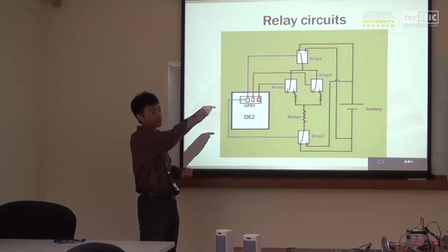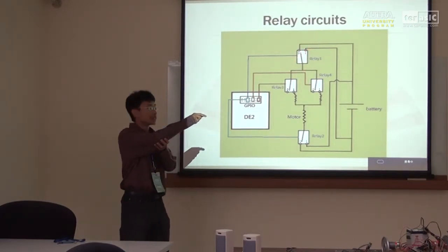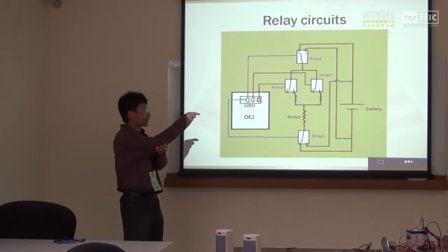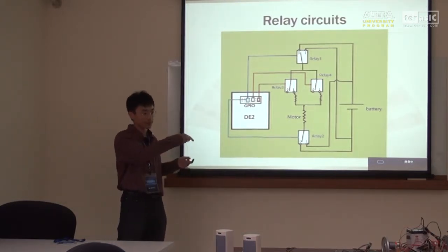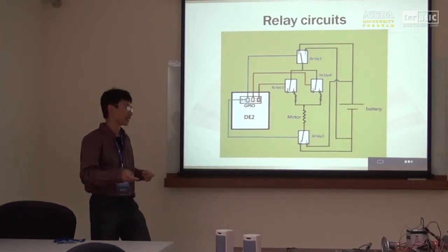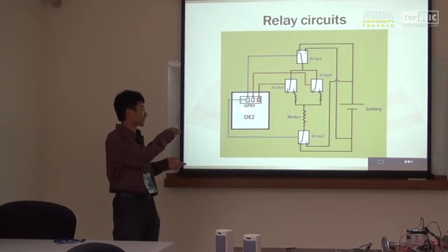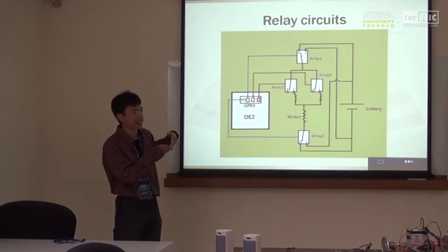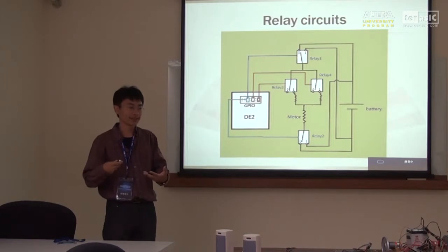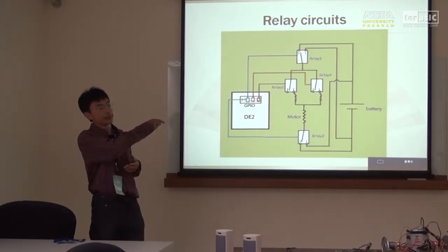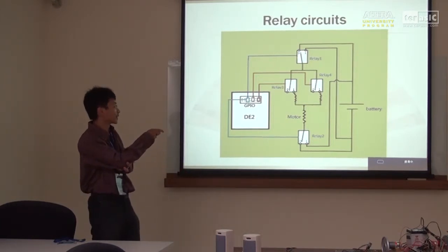The switch will turn from 0 to 1. And this current is provided from the GPIO port. We tested it several times, and we found that two GPIO ports will provide enough current to make the relay go from 0 to 1.